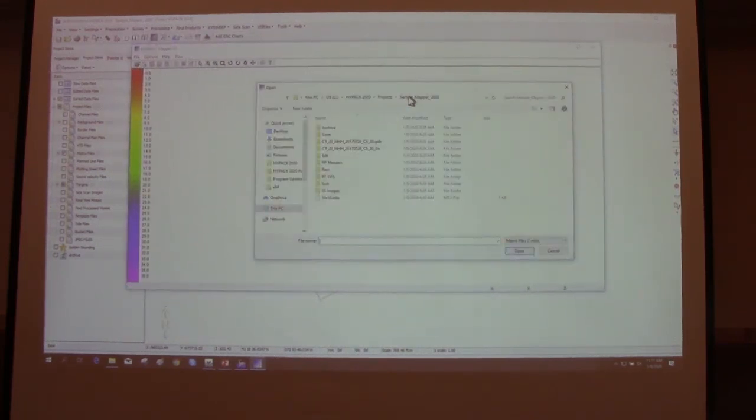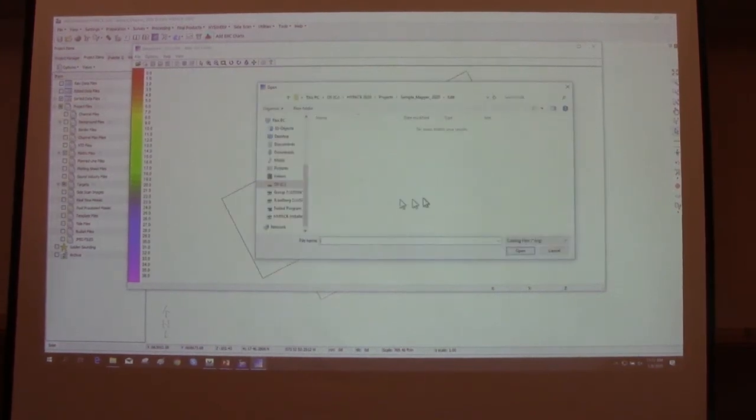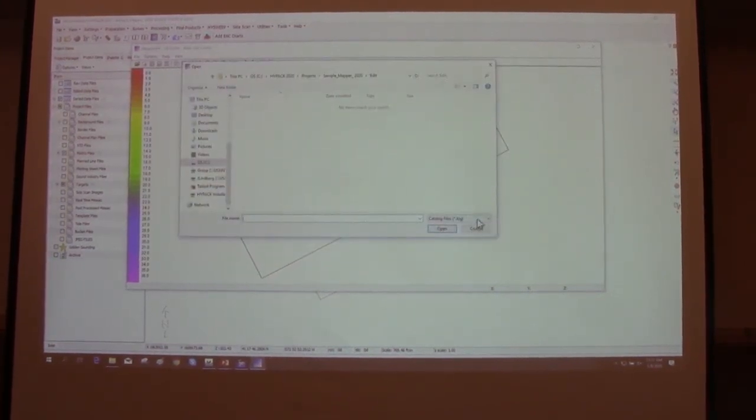We'll hit the open folder. You'll see that I have the drop-down menu. I have to load up a matrix first, and then the next thing is going to prompt me for my data. If you hit the drop-down menu over here, you'll see the different types. You have a log file, so again, that could be single beam or multi-beam log data, XYZ data, EDT files, which are our single beam edited files. Individually, you can bring those in if you want. Just the individual multi-beam files, matrix files. If you take a high density matrix, you want to make a lower density filled matrix, you can do that.